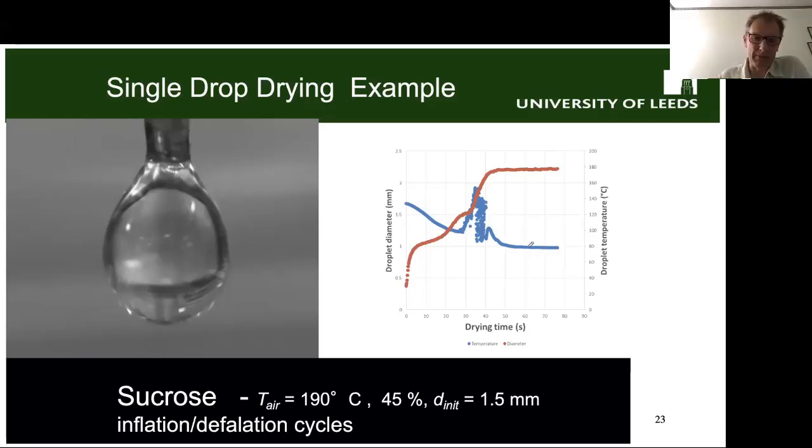So what's happened there is the material properties of sucrose have remained relatively liquid-like, shall we say, at these moisture contents. So even though the drying has slowed down within the droplet, the material properties are more liquid-like, more viscous behavior, and that's resulted in seeing no kind of evidence of the puffing in the final droplet.